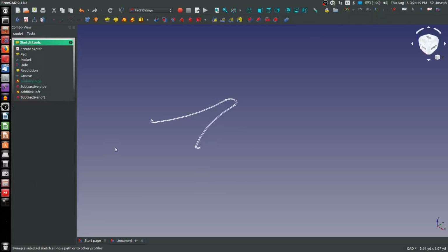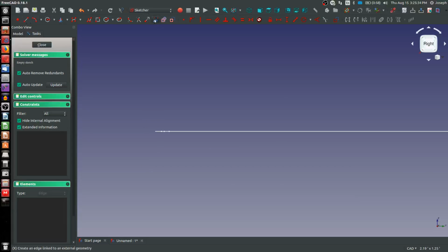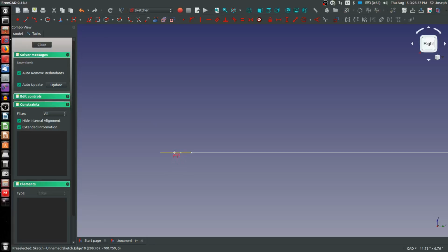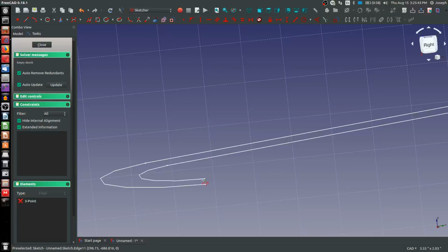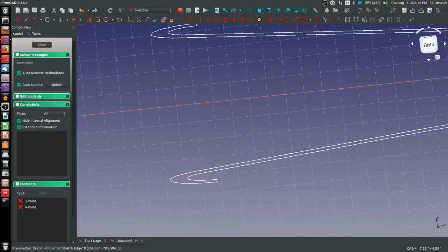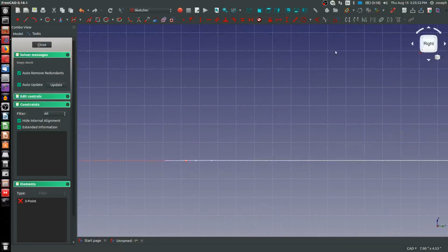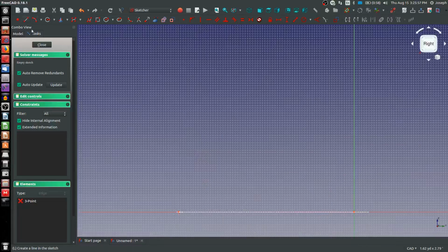You can see there's our pre-existing sketch. So what I want to do, and this is going to be kind of arbitrary, is edge import my leftmost point. That can be imported. There we go, there's one. Can I import another one? Yep. Okay. So there's my leftmost point. I'll delete this. We'll get normal to the sketch. And I'm going to create a line. Vertical line.